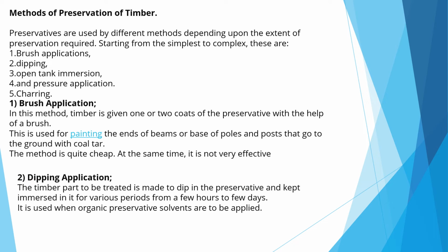Next, dipping application. The timber part to be treated is made to dip in the preservative and kept immersed in it for periods varying from a few hours to a few days.